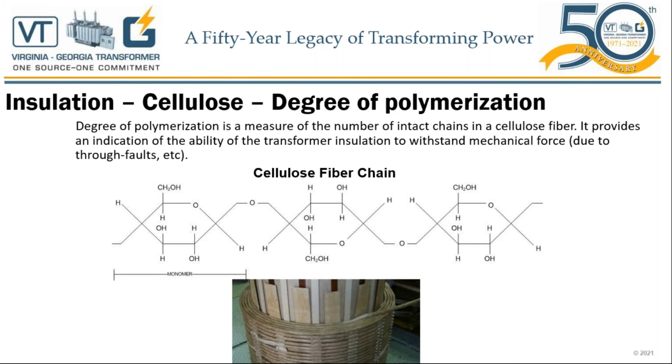Because what happens when the average winding rise goes beyond 65 degrees, or the ambient where this transformer is operating goes beyond 30, 40 degrees, which as we know, in summertime in hot states, the ambient will be over 30 degrees. Summertime, hot states, we're going to overload these transformers. So what do you expect the temperature to be in the windings?